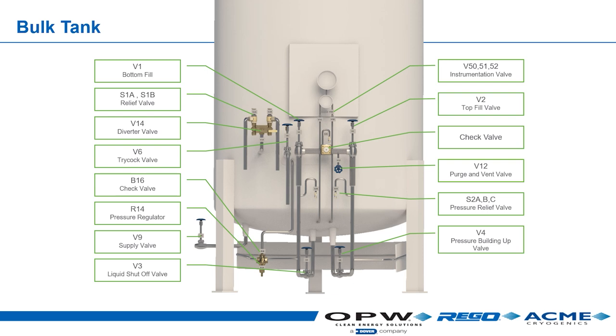If he comes in and delivers that whole thing in the bottom, he's going to create more pressure in that headspace. So the top fill allows the liquid to splash down and fill it from the top. When you fill it from the top, you're collapsing that, you're turning a lot of that gaseous headspace into liquid, which means you're lowering the pressure. So the driver's manipulating a top fill and a bottom fill to make sure he's maintaining what pressures are needed during the time of the fill.